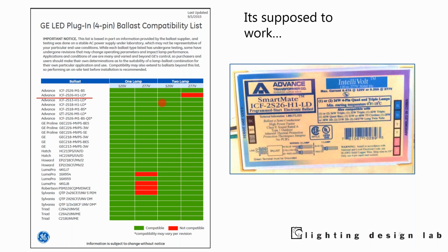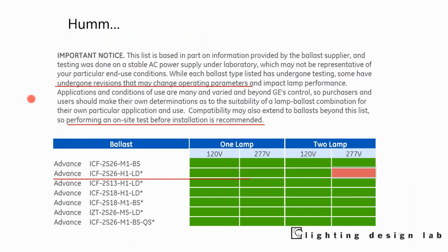It's only not compatible if I have 2-lamp 277 volt, but I don't have that. I have 120 volt 2-lamp. So it should work, but it didn't work. So I'm like, wonder why.